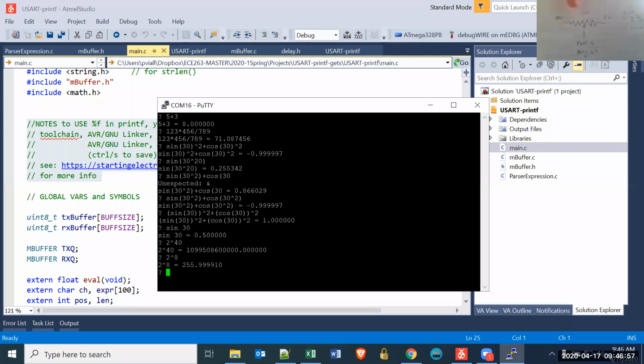On one side, we've got 0 volts connected to that resistor. On the other side, we've got 5 volts. And one way to picture this is just a bunch of high resistance wire that's wound around a non-conductive core. The potentiometers on your board, or the volume controls on your board, are 10K. So we've got a 10K resistor connected between 0 volts and 5 volts.